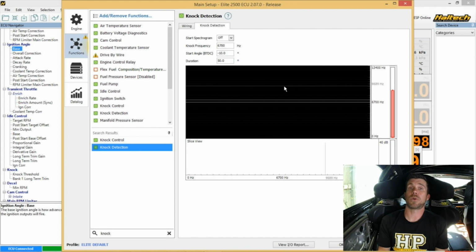So if, for example, our calculated frequency there was 6 kilohertz, the second harmonic would occur at 12 kilohertz. Now, the reason that the factory OE manufacturers use a tuned sensor like this that looks at the second harmonic is it improves the signal to noise ratio, so we're less likely to see interference from background engine noise at that second or even third harmonic.